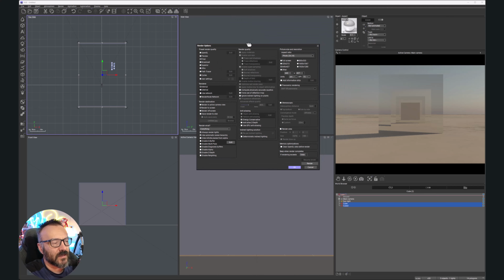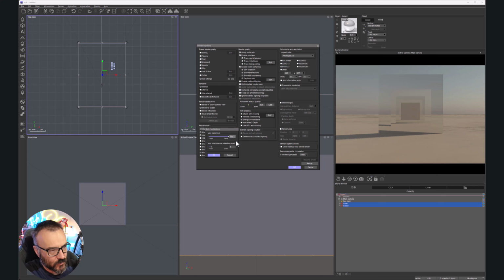If we're going inside the render options, let's go to user settings because I want access to the reflection trace. We'll click edit. And notice right here, we have it 5, 5. So it's maximum trace level 5 and 5. So it's meaning after 5 times, it disappears. Well, you know what? Let's go crazy. Let's select 50. Well, technically, I don't recommend if you have a complex scene because remember, it needs to calculate all of this and take quite a bit of time.